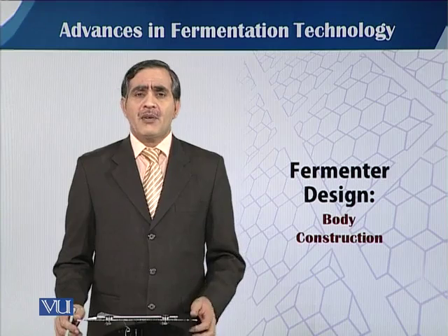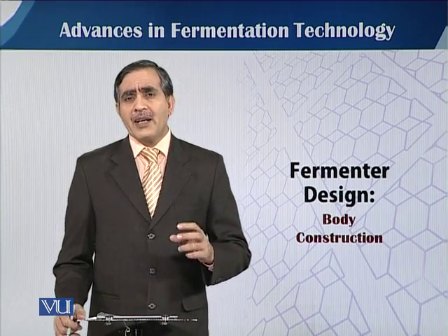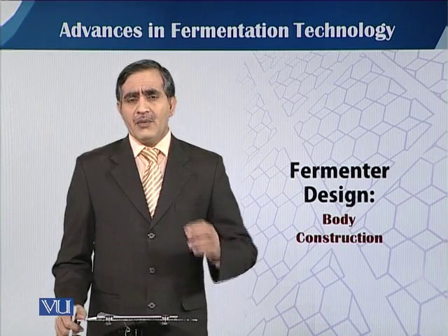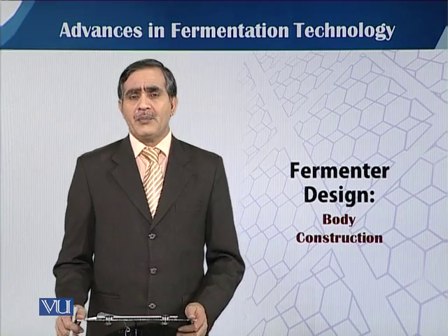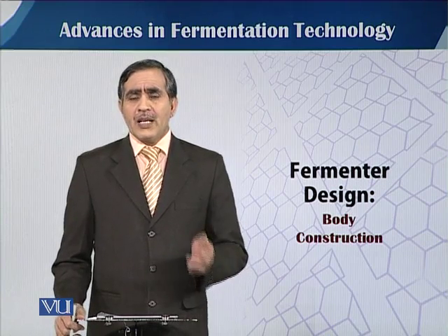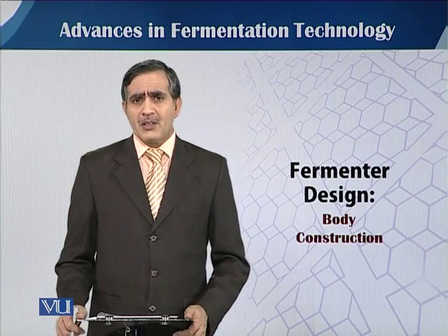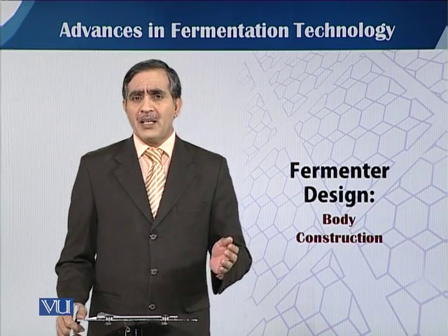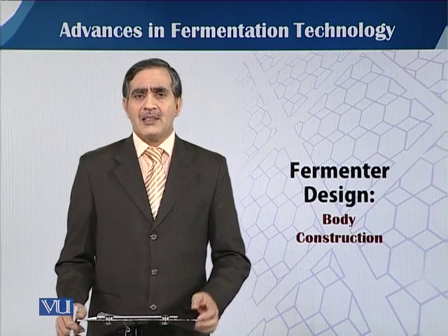while talking about the 13 basic characteristics of a fermenter, one characteristic was that when we design a fermenter, it should have an identical geometrical shape. That can facilitate the optimization process when we go from the lab scale to pilot scale and then to industrial scale.